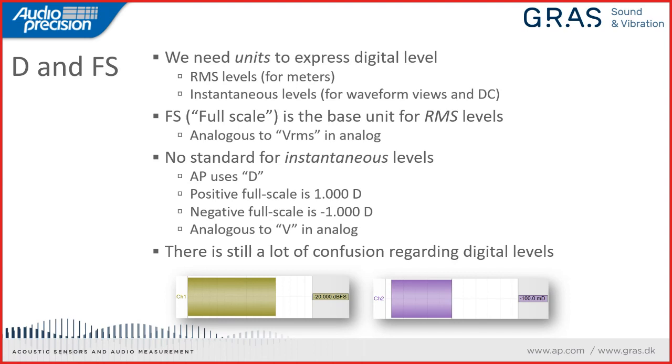The reason we have these 2 units is in the physical world, in the land of volts, volts is both an instantaneous unit and an RMS unit. In the digital world, for historical reasons, FS, or full scale, is only an RMS, or root mean square unit.